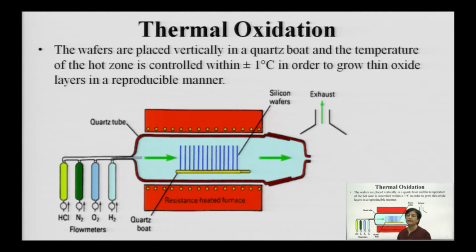Now, here, and that you must remember basically. Here is the furnace which is being used. It is a horizontal furnace, similar to our epitaxial growth process. But here please understand, the oxidizing species arrive not parallel but perpendicular, normal to the wafer surface.